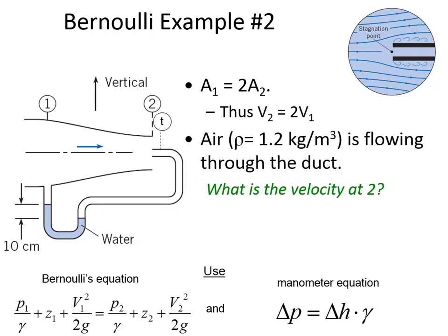No, there wasn't a differential manometer in the experiment on Tuesday. There was a piezometer. So in this nozzle, the air is flowing through the nozzle, and we're using water as our differential manometer fluid. And water is more dense than air, and so it works great as a manometer fluid. And the other thing is that you can see the water, where you couldn't have two gases. You couldn't have one gas as the manometer fluid and another gas going through there, because the two gases would mix. So just that as a preamble.